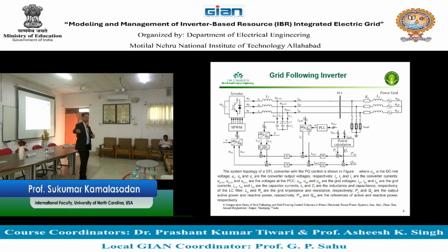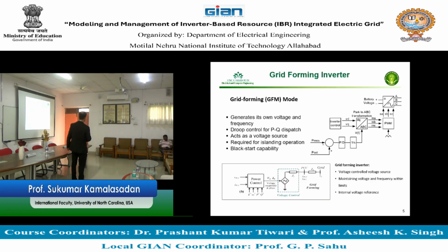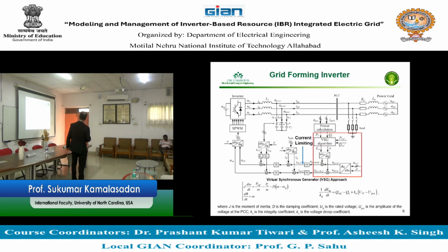The one which is getting the angle from the electric grid and then doing its job is called a grid following inverter. The same inverter can do grid forming and following. So then we will say, hey, my inverter has two modes of operation. One is grid forming mode of operation, second is grid following mode. So this is how you do grid following. To do the grid forming, you can generate these voltages and angle.